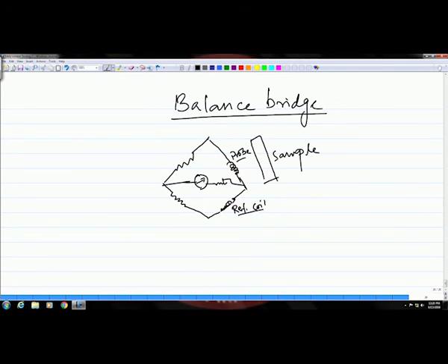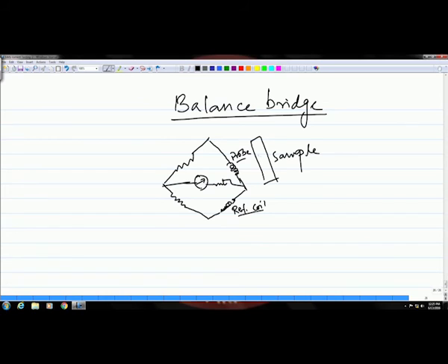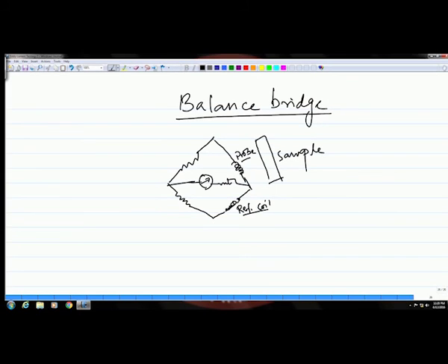On the other hand, if there is any defect on the sample, then there will be a change in this coil, in this probe, as we have seen before, and due to that change, now since the reference coil is kept constant, there will be a differential signal between the reference coil and this probe due to that change, and as a result of that this detector will sense a change. So, it will pick up a signal, and that is what is going to be used finally for the eddy current system to make indications about the flaws.